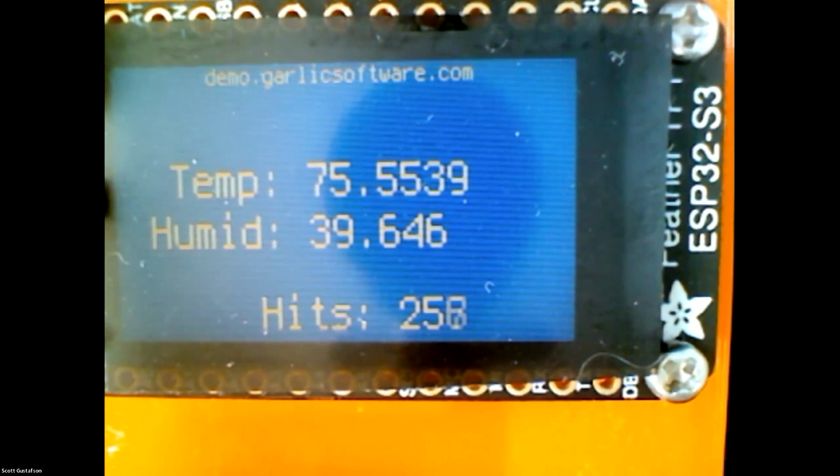So if anybody is interested, there's wire called magnet wire, which is copper wire that has enamel over it. And there's some super, super thin variants. And actually, that's what I'm going to run in the pole to get the power from the base. So I'm going to 3D print a new base that'll hold my battery and my microcontroller. Then I'll just run the little magnet wires up the pole into the light fixture.